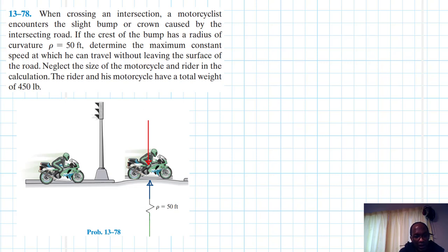This is our n-axis, and this one is our t-axis. Of course, along that direction we don't have any tangential acceleration. The tangential acceleration is equal to 0 because the speed that we are about to calculate is constant. So this is W, which is just equal to mg, and this is N. Small n is for the coordinate system, n for normal, and t for tangential.